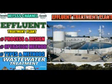The principle of operation of an ETP is physiochemical treatment followed by polishing treatment like sand filtration, activated charcoal treatment, or adsorption. So like this, we have to remove all the effluent, and wherever the sludge is there, we have to remove it through the pre-primary, primary, secondary, and tertiary treatment processes. So this is a clear picture of the effluent treatment plant.